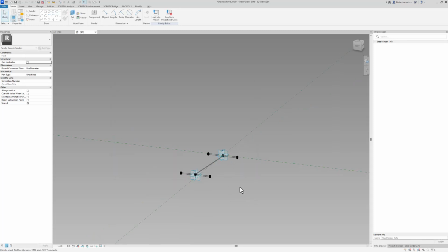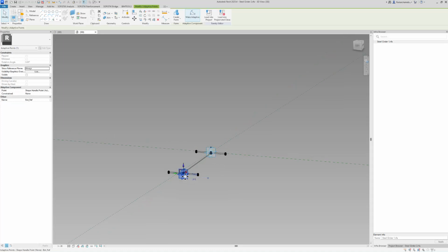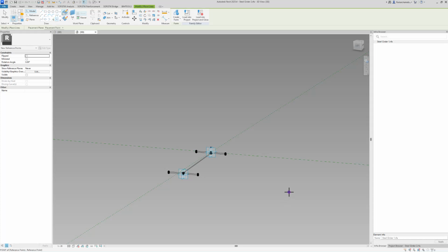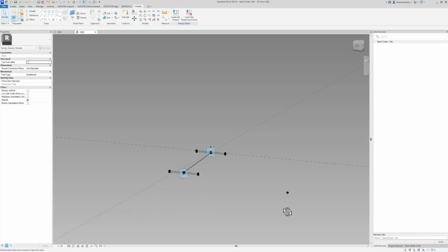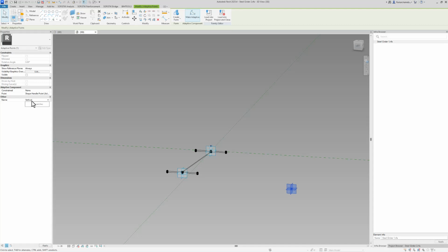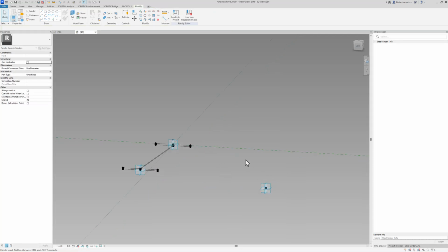What is now necessary for you to easily reference only the vertical deflection? You need to assign another shape handle point. I do this by referencing the vertical plane and placing a point anywhere in this plane. I select it and change it to a shape handle point. And by assigning it a name, which I will call vertical, underline only. That's actually all that's necessary from the shape handle point.